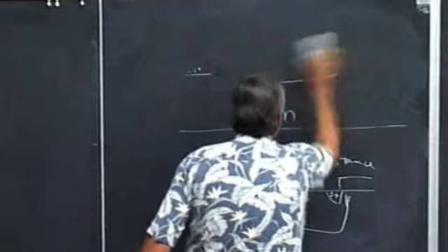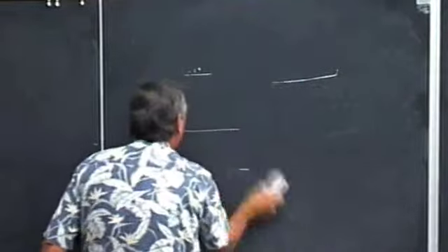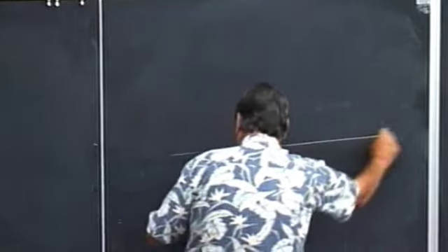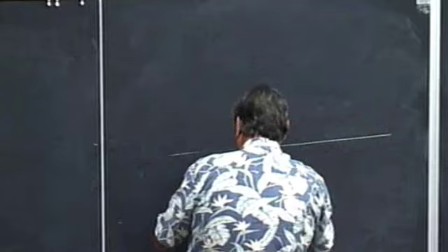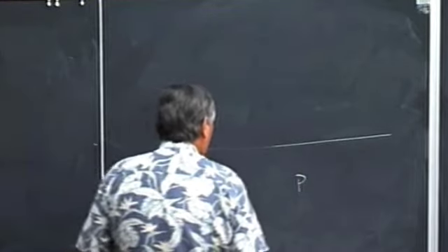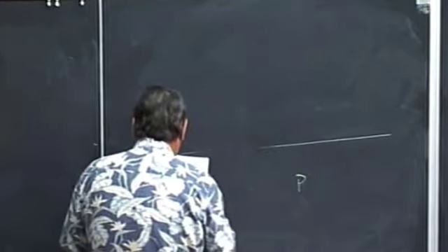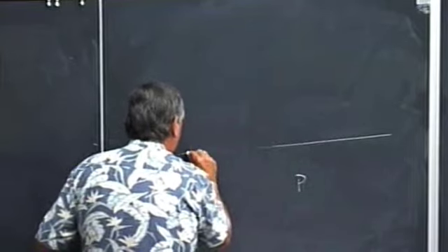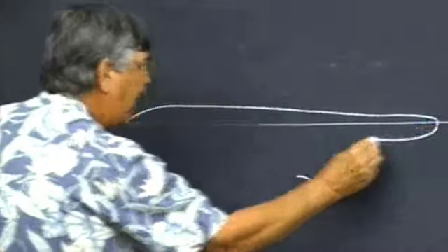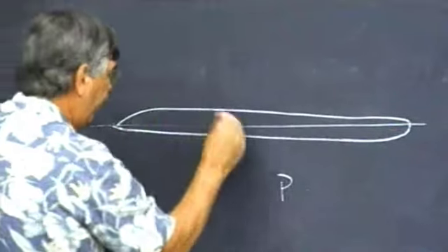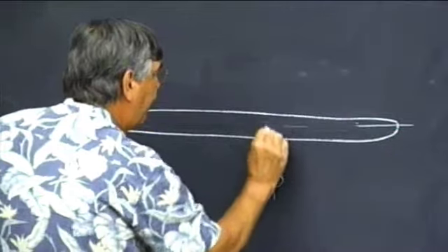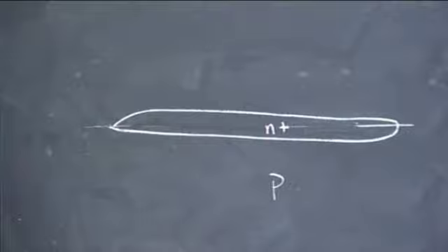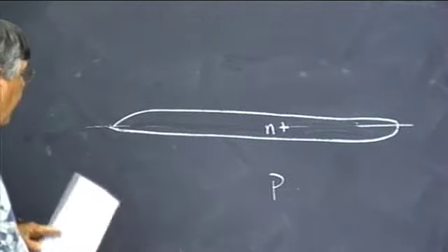How do we get it? In the standard buried collector process, we have a so-called buried collector. We start with lightly doped P-type material, 10 to the 16th per cubic centimeter boron. Moderately doped, fairly light. Before we do anything else, where we know the transistors are going to be, we will put a so-called buried layer in. It's going to eventually end up growing above and below because there's going to be some stuff above. We put a lot of electrons around this region, and this forms a so-called buried layer. I'll explain why later, but that's an important part of the process.